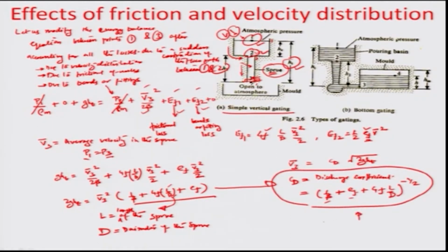As I will show you in the following iterations, the discharge coefficient here can be generated in an iterative way, because at the outset you probably just have a first guess of the Reynolds number, and that may not be the accurate velocity, because the velocity has to go through all these different terms.